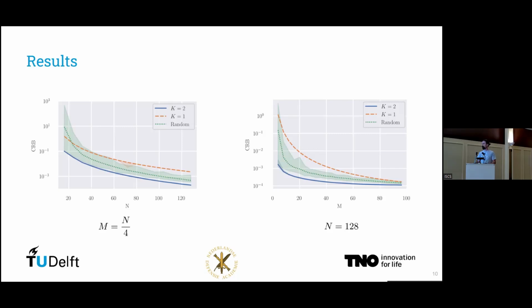For the extensions, the big one, I think, is trying to apply this to planar arrays, because linear arrays are not super modern. For planar arrays, we found that the Cramér-Rao bound doesn't just depend on the angle differences, only for some planar arrays. So what we're trying to figure out is what the necessary conditions are for planar arrays to also depend only on the difference of angle of arrival.